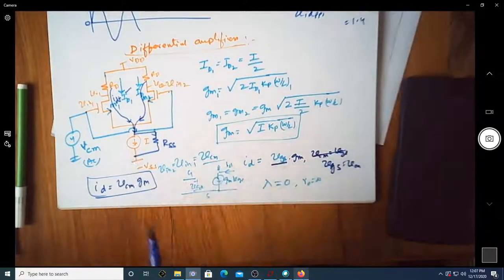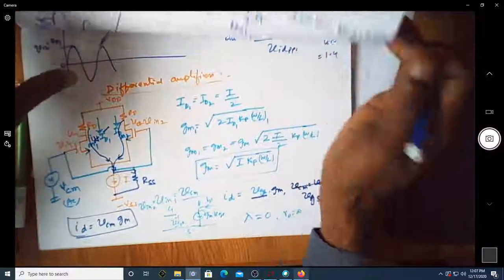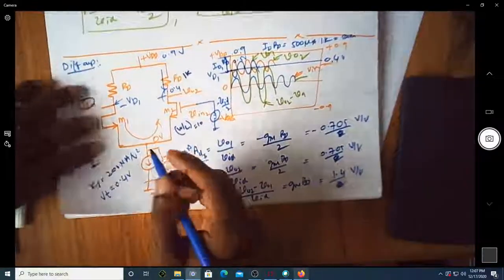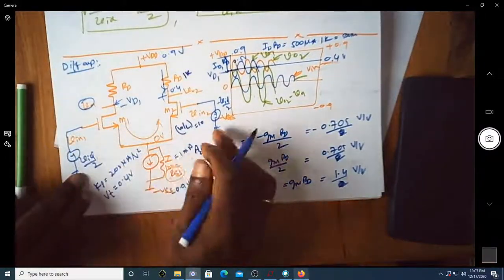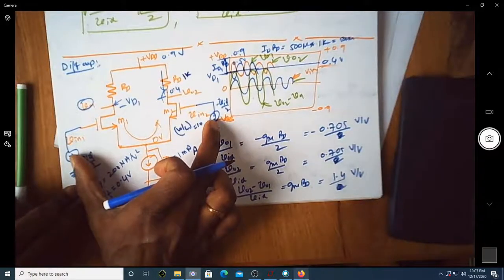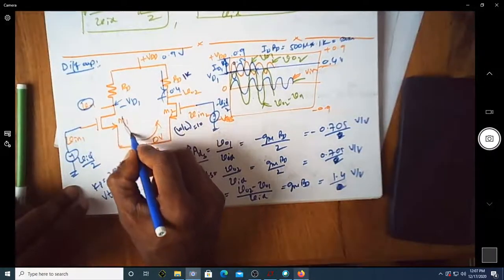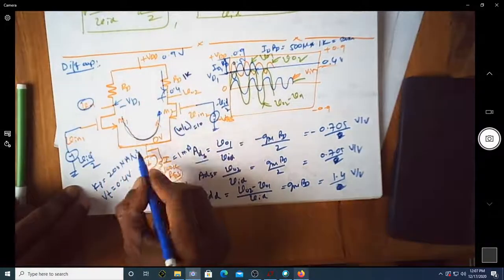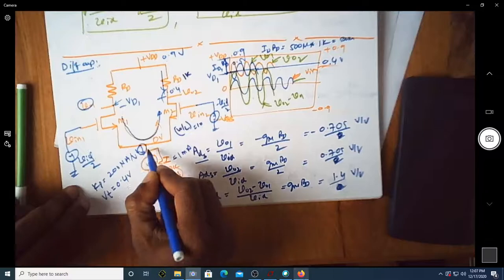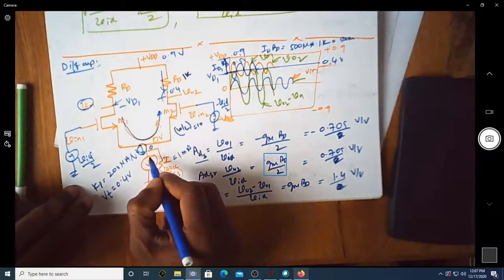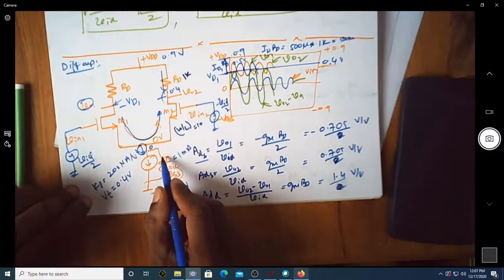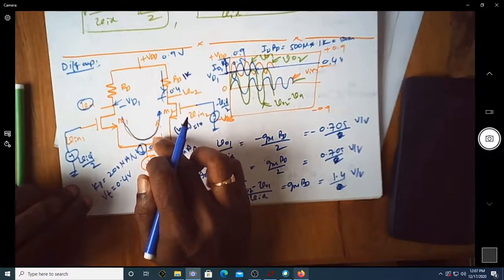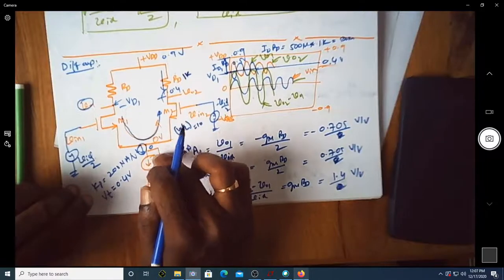But in case of your differential input voltage, as we discussed in the previous differential amplifier, since the applied voltages were out of phase, the current was actually going back into your M2. This was the direction of flow. There was no current flowing. The DC current that was flowing here was actually 0. There was no current flowing through this RSS. The voltage drop was 0. So that's why we could write 0 volt, because there is an open circuit and no drop happening here.